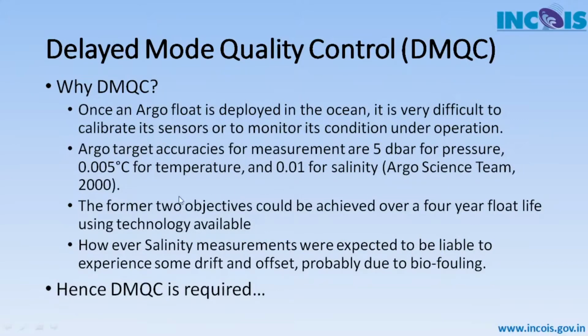As I said in the beginning, there are preset accuracies for these floats, and whether we are able to maintain them or not has to be seen based on the data only, because the floats cannot be retrieved. Once a float is over a year old, there is obviously some sort of biofouling happening on the sensors, and this can cause some degradation in sensor quality. So we need to check and then do this delayed mode quality control.